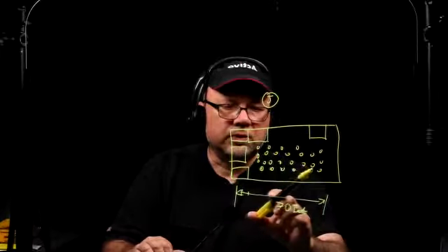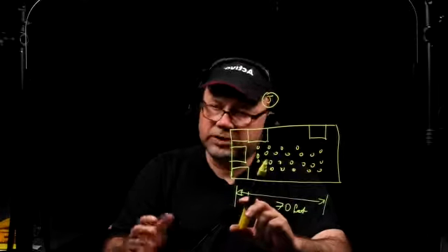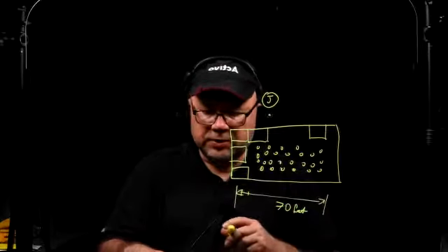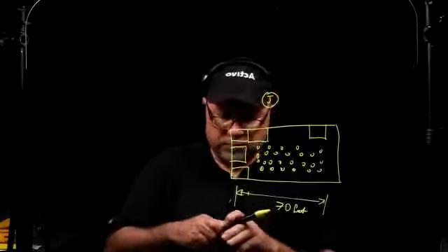All right, so you're going to have that. Now, when you have all the hooks 4 feet apart, then when it comes to calculating the distances of the cables, you are going to just count the J hooks, 1, 2, 3, 4, whatever, multiplied by 4, and here's the number of feet. So the cable calculation is going to go nice and easy for you.